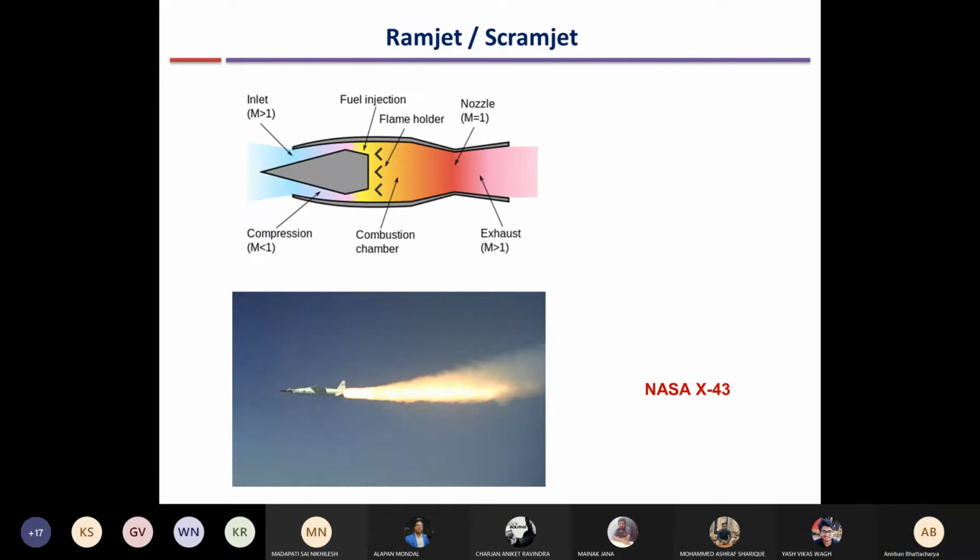No, sir. Okay, so if I want to design an aircraft for even higher velocity, say not Mach 3, say I want Mach 6 or Mach 7, a very high velocity. The incoming air will come at a very high speed, and if you want to reduce the speed to subsonic speed, a lot of losses will occur. It's not very easy to reduce from that kind of speed.